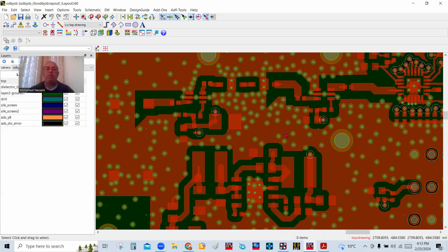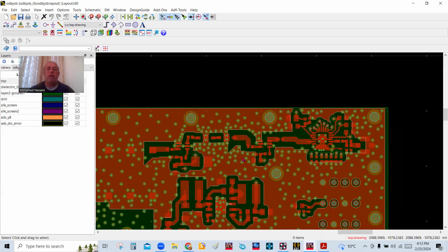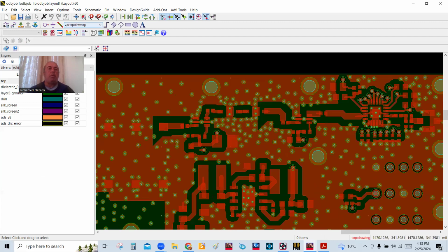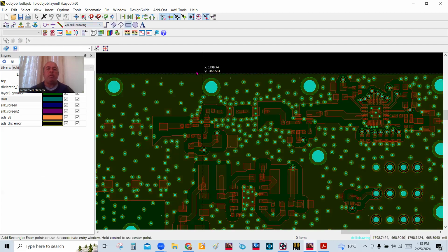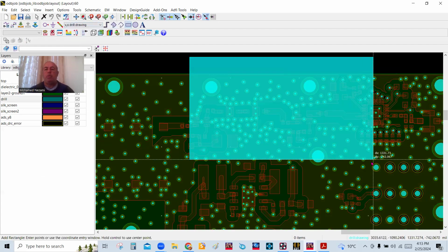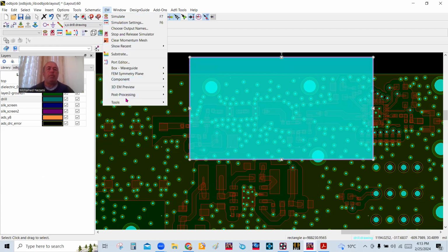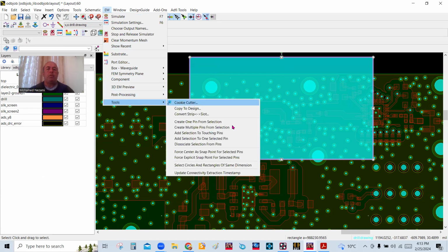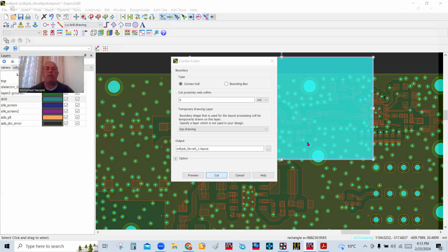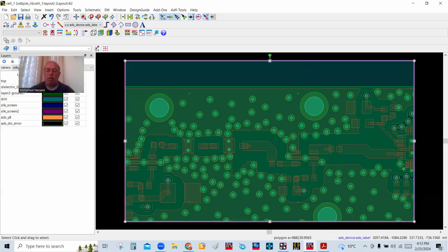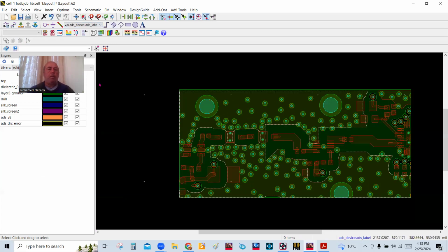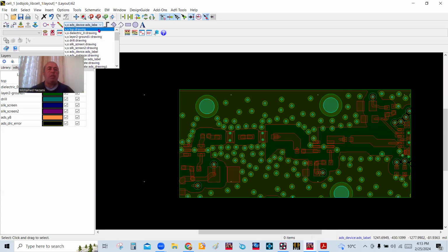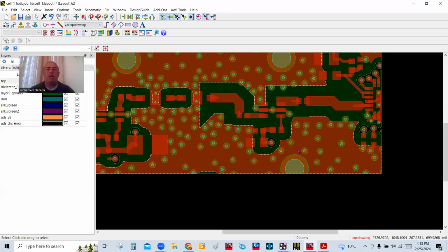And we're going to chop this part here and analyze it, okay? So we're going to go like this. We could do it, let's go this way. And so we're going to go to here. Okay, I'm just going to use arbitrarily any of the layers to create a zone. And we're going to go to tools, cookie cutting, and we're going to cut that out. So right now, I've only got this portion here, and this is basically the portion that contains the IF stages.